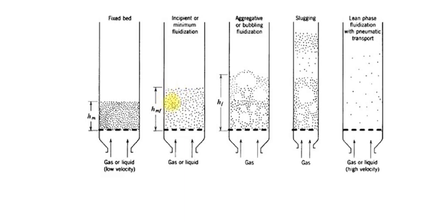That point is called the minimum fluidization velocity. This is the point where the buoyancy starts to overcome the gravity. At that point the velocity is called the minimum fluidization velocity, and the pressure drop across the bed is called the minimum fluidization pressure drop, the required fluidization pressure. Now, what happens if you plot the velocity versus the pressure drop?